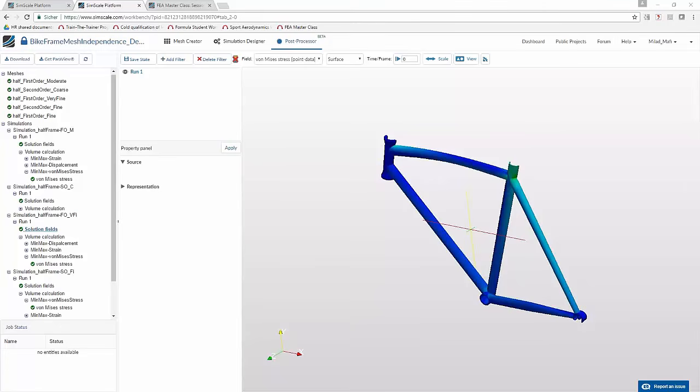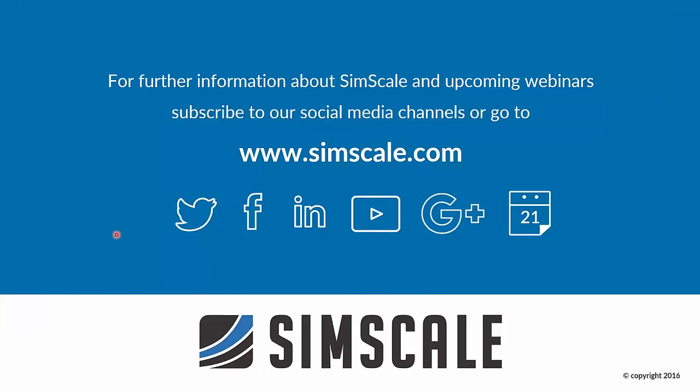Hossein, that's a very good question. First, good news is you don't have to pay any price since SimScale is free, but let me answer your question. You're right. In theory, if I just increase the global mesh size and have a very, very fine mesh which is mesh independent, my problem seems to be solved. But you should not forget, in reality, a lot of times you want to perform a parametric study with the model, or you want to test several conditions.